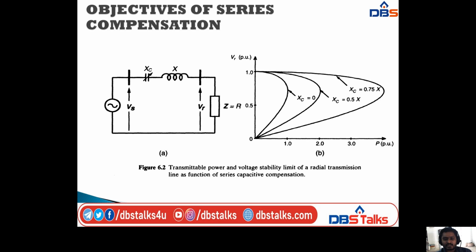Here we draw the characteristic diagram between receiving end voltage versus power. Both values are taken in per units. The power is taken in per units from 0 to 3 per unit, and the receiving end voltage is taken between 0 and 1. Here I draw three curves. The three curves are drawn when the capacitor reactance changes, that is when X is equal to 0 we have one curve, when X is equal to 0.5X we have one more curve, and when X is equal to 0.75X we have the last curve.